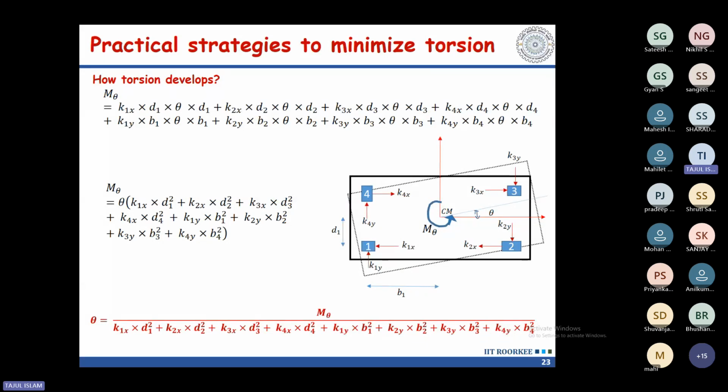For example, initially your member distance from the center of mass was 100 mm. Now your member is at a distance of 200 mm. So for the same stiffness, without changing the member size, it will give you four times the effectiveness in resisting the torsion. So this is what you can understand from this.